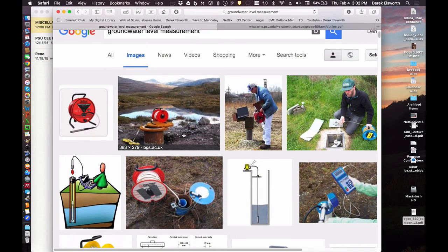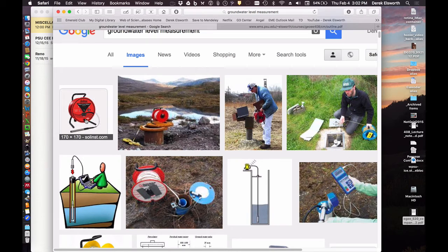Typically, a couple of different ways. The most common is to use a water level meter, just a little sonde that has electrical cable attached to it, which is graduated in terms of length. You drop it down the hole and you reel it down. It has two conductors on it, so it's a flat piece of ribbon that has a conductor down each side, along with length measurements on it. The little sonde at the bottom has a hole in it which lets water in, and it has an external sheathing with an internal cone, and they're electrically separated from each other. One is connected to the one conductor that goes up the ribbon. The exterior is connected to the other one. When it hits water, it bridges the gap between them, makes a circuit, and a light bulb comes on here, and you know that you've hit water.